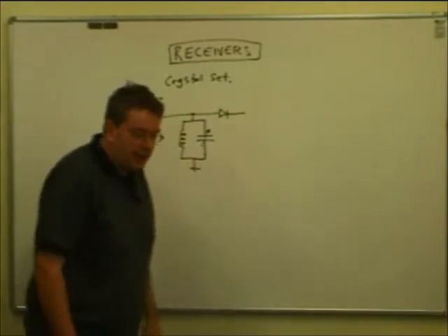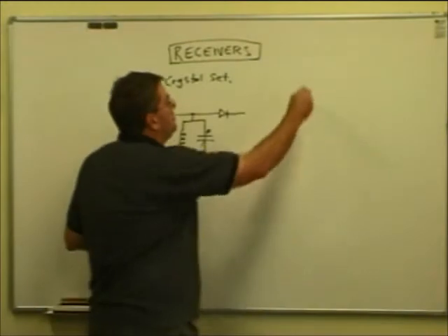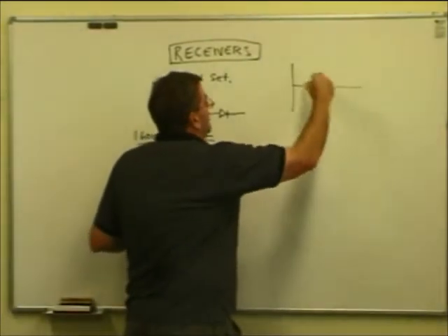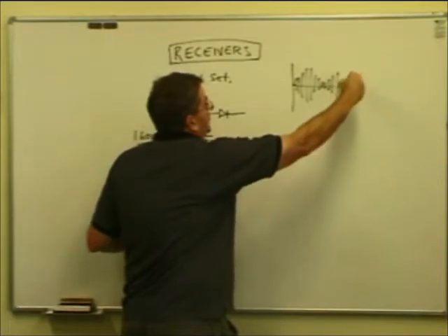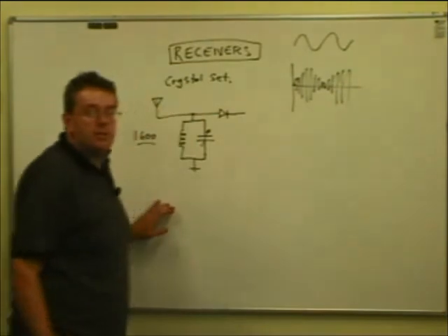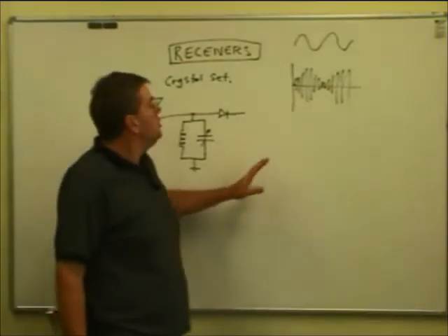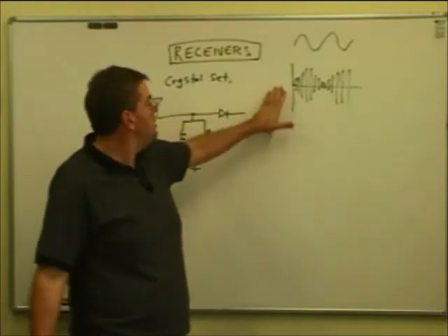Now, remembering that an AM signal has that appearance, remember the AM envelope, the carrier wave superimposed with the modulating signal, so that can be the modulating signal there, the intelligence, just a straight sine wave, maybe a tone. If it was music or speech, it would be more complex looking than that, but it will do for the explanation.